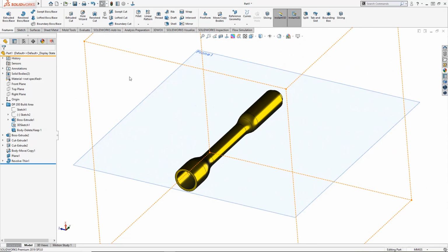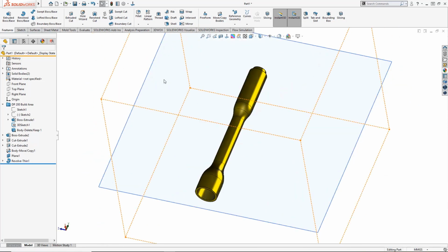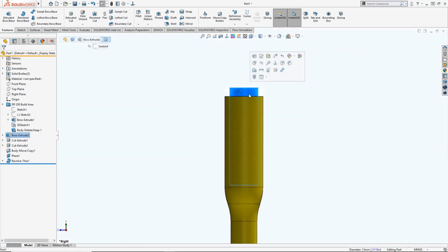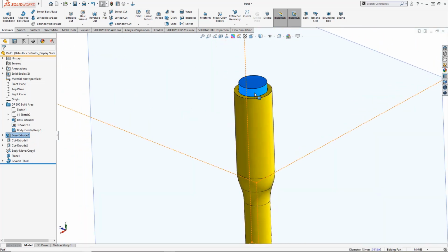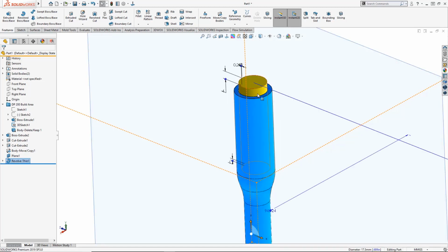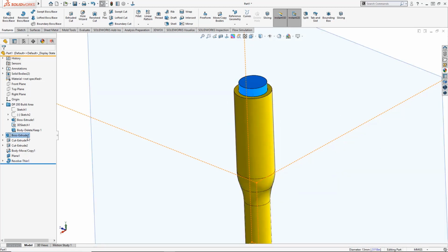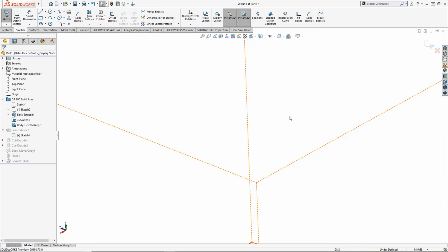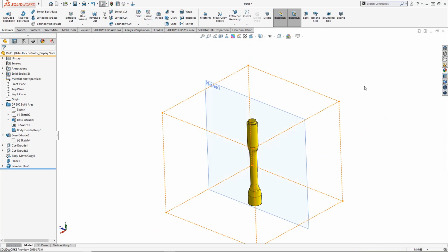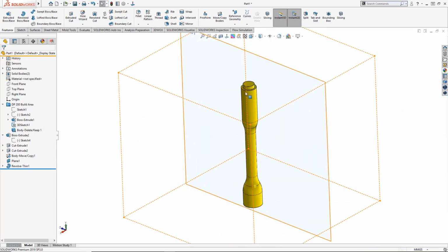So next thing we've got to get out of the way on this particular model is maybe go ahead and think about some of the next features that are coming up. So we're going to have to build a fin. We're going to have to go ahead and build some other things. But to go back to what I was talking about a second ago, we built this as a multi-body model. What I have here is this rocket motor that we sketched down in the top plane, and then I moved up into this position. One of the little idiosyncrasies you get there is that when you double click it for dimensions, the dimensions aren't actually where the motor is. The dimensions are where the original feature is before it was moved. So make sure you zoom out when you see things like that.